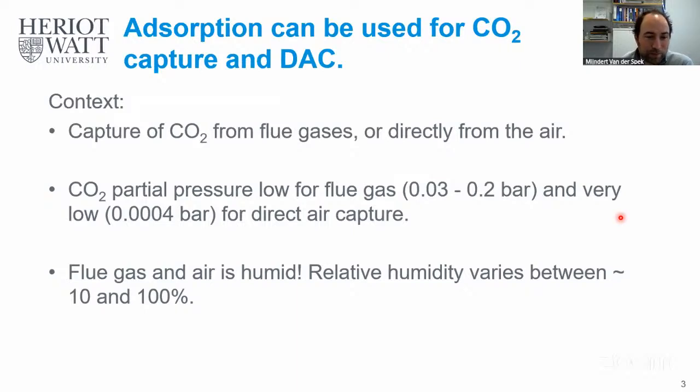And then, really important is that flue gas and air is humid, and relative humidities, for instance, across the globe vary between 10 and 100%. Even in deserts, there's usually some humidity. Flue gases, when they enter a capture plant, are usually saturated in water, so they're about 100% relative humidity, right? So humidity is critical, and to my mind, really insufficient research has gone into the effects of water on adsorbent and adsorption processes.